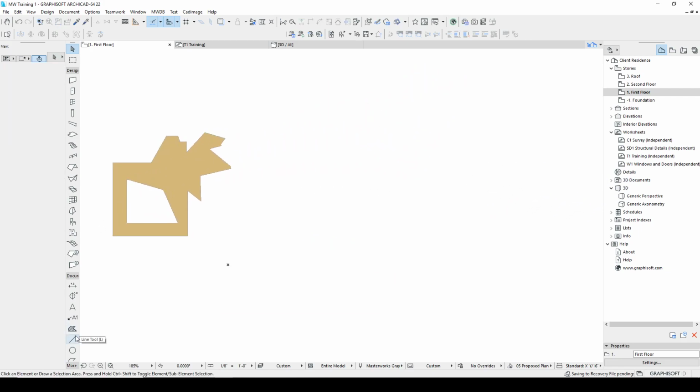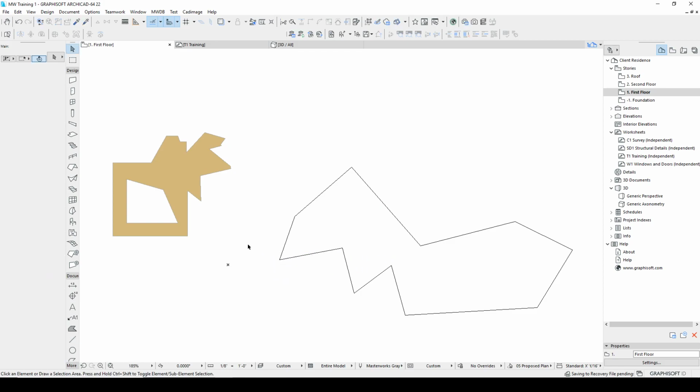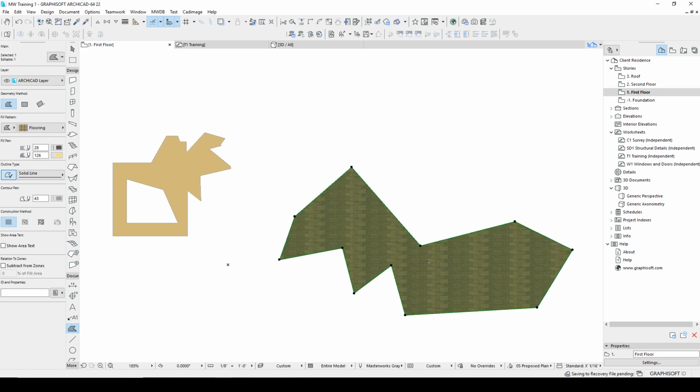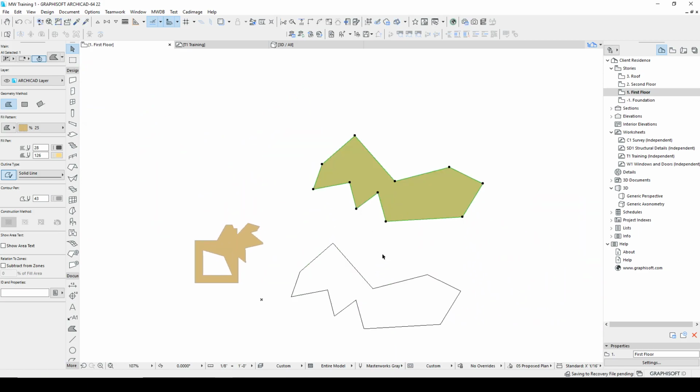A couple things to consider. One thing is you may do some complicated shape. I may use some lines just to lay out some geometry. I split this, and whatever I ended up doing, and then maybe I trim these guys, and then I can go to the fill tool, select my default settings, and then I can hold the space bar so I didn't change my default. So I'm going to pull these in as to my default and inject that in there. So I can take those lines and convert them to the fill with the magic wand.